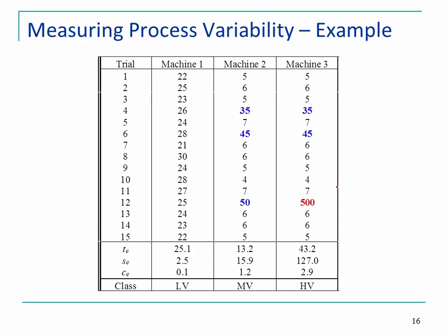And for the second case, it's not as bad as the third one, and you can see why the third one is getting that high variability, because you have a 500 among numbers that are most of them less than 10. Okay, so you can see the effect of having those outliers in your processing time. So most likely here what happens is you end up having a failure in your process, and that processing time is taking into account that time for repairing the machine.